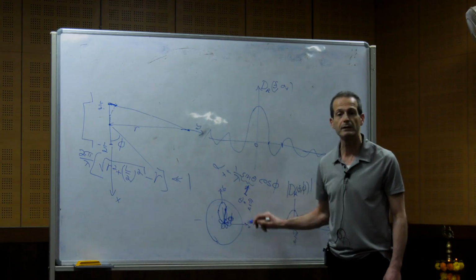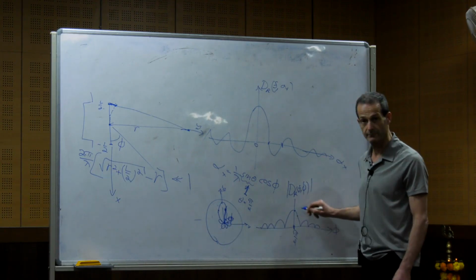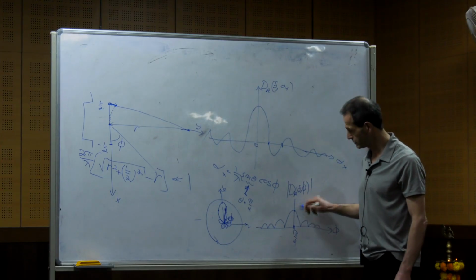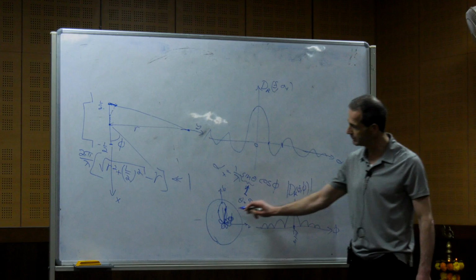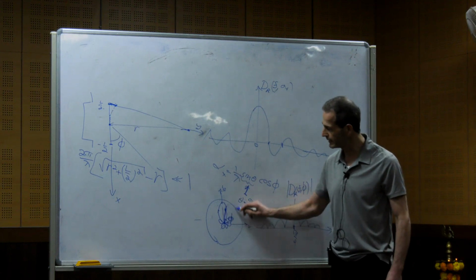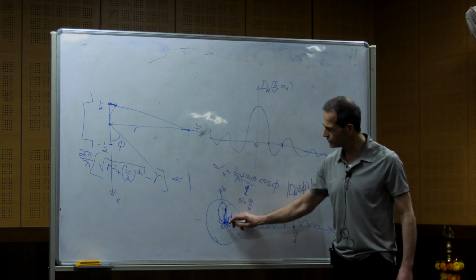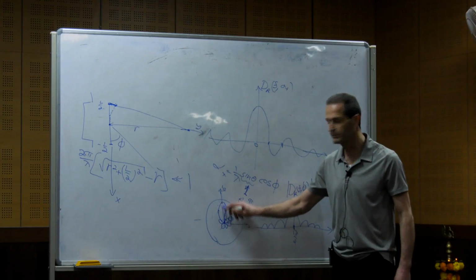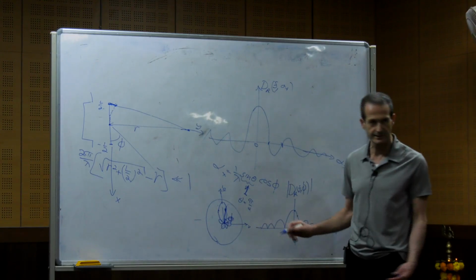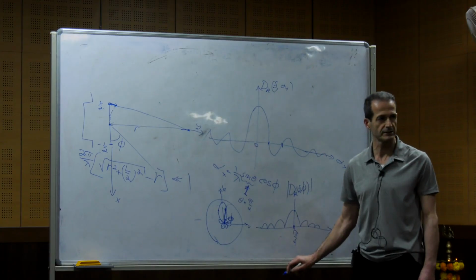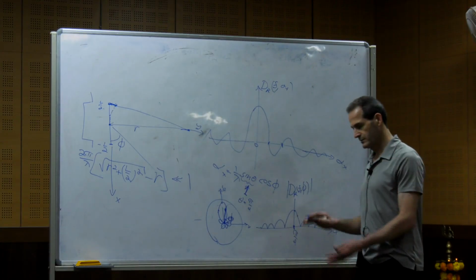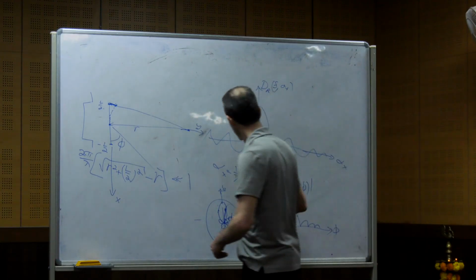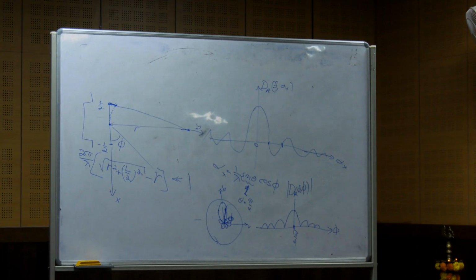But here we do it in dB. Also here we can change that to dB, decibels. It doesn't have to be linear, but here it's definitely in dB. So this distance is in dB. And usually we need to limit the range of dB because we cannot show something that is 0, which in dB goes to minus infinity. So we can limit the range of dB that we want to show on this plot. And this is very common to show a directionality pattern.